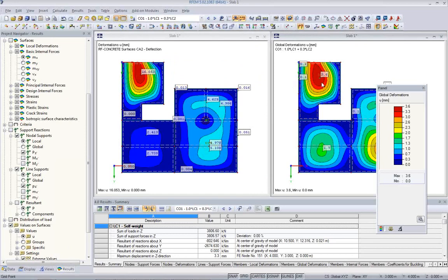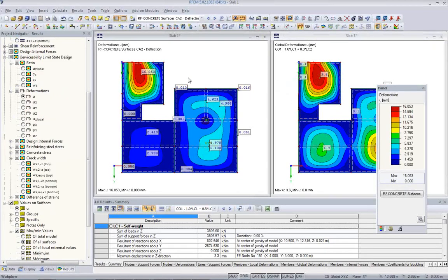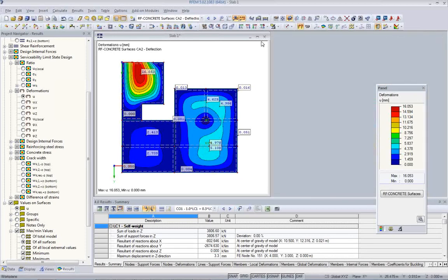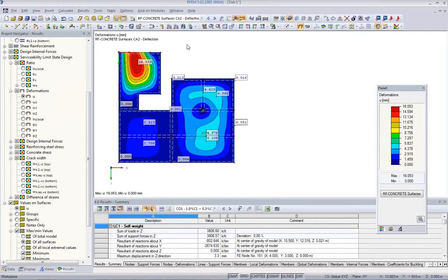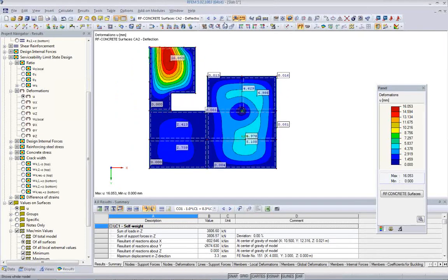So we have about 4, 3.5 to about 4 times more of the deflection, between 4 and 5 times more of the linear deflections we have in the nonlinear situation. Okay, this was this question, and then let's take a look at the punching check.